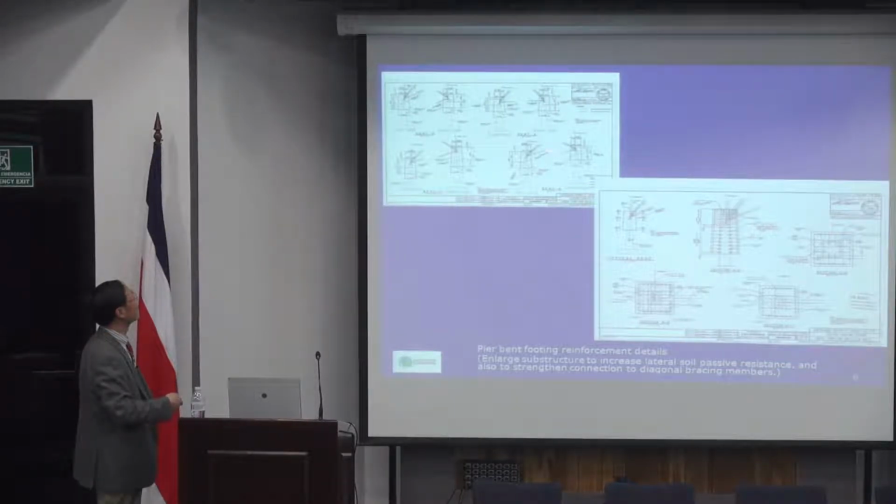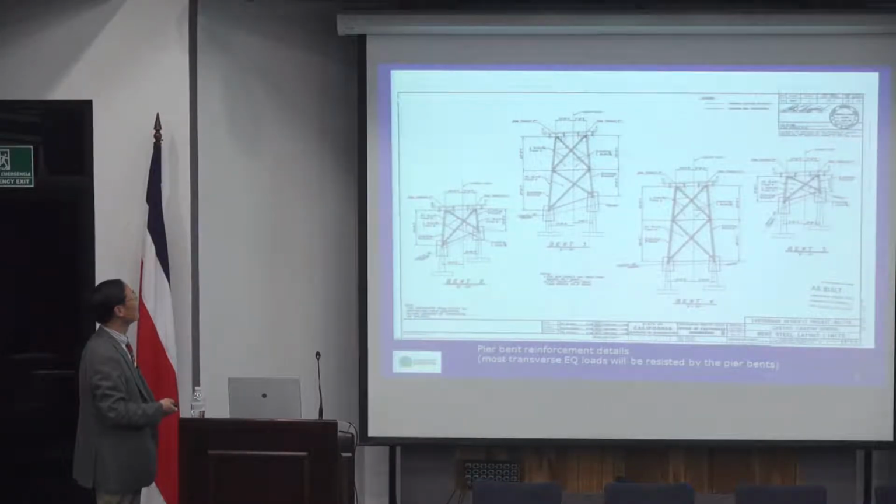They found that there's an insufficient connection at the joints. To increase joints, you could just simply cast reinforced concrete to cover everything, so to make that monolithic, so that the weakness of the connection will become non-consequential. And these are just sketches of how they fix these bents.